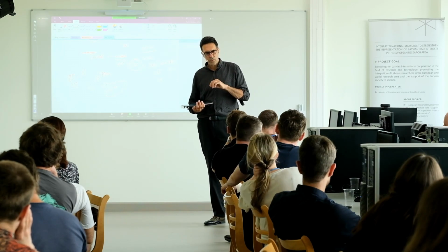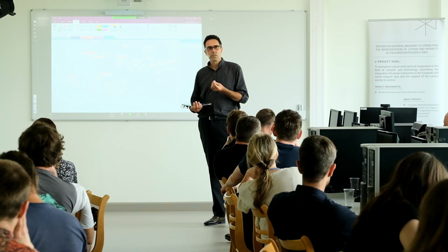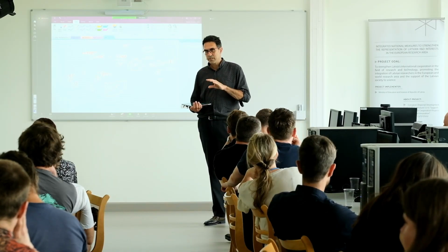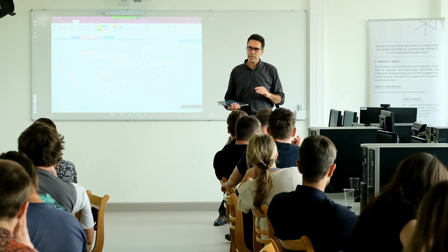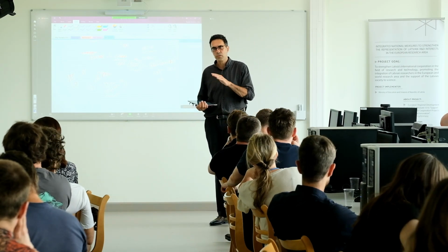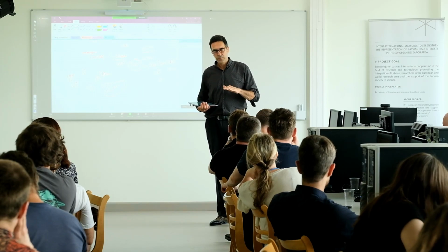Just to be exact, for the positioning we use the ellipsoid. So that is not a geoid. The geoid is known, right? But we use the ellipsoid here. And that means that we get geocentric coordinates. That is not the same as leveling coordinates, because these are orthonormal values that depend on gravity differences. So this is purely geometric. That's the first part of my answer.